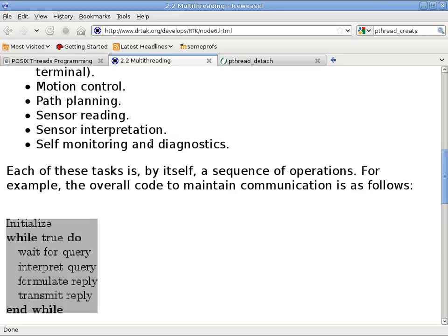Okay, and that threshold is important because the logic part, or the brain part, of the robot has a reset controller which monitors the incoming voltage. When the incoming voltage drops below a certain point, it will say, oh, this is not a safe voltage anymore, because the processor requires at least this much voltage to operate. When the voltage drops below that point, it is no longer reliable. So it holds the reset line of the processor, which basically means the processor is held in a reset state, which is a quote-unquote safe state because it won't be executing anything funny.